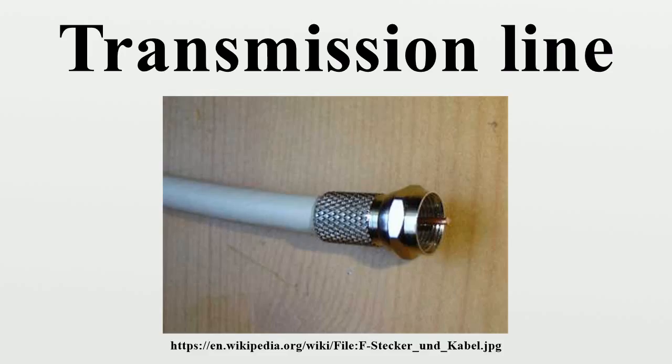In such cables, many pairs are grouped together in a single cable, from 2 to several thousand. The format is also used for data network distribution inside buildings, but the cable is more expensive because the transmission line parameters are tightly controlled. Star quad is a four-conductor cable in which all four conductors are twisted together around the cable axis. It is sometimes used for two circuits, such as four-wire telephony and other telecommunications applications.